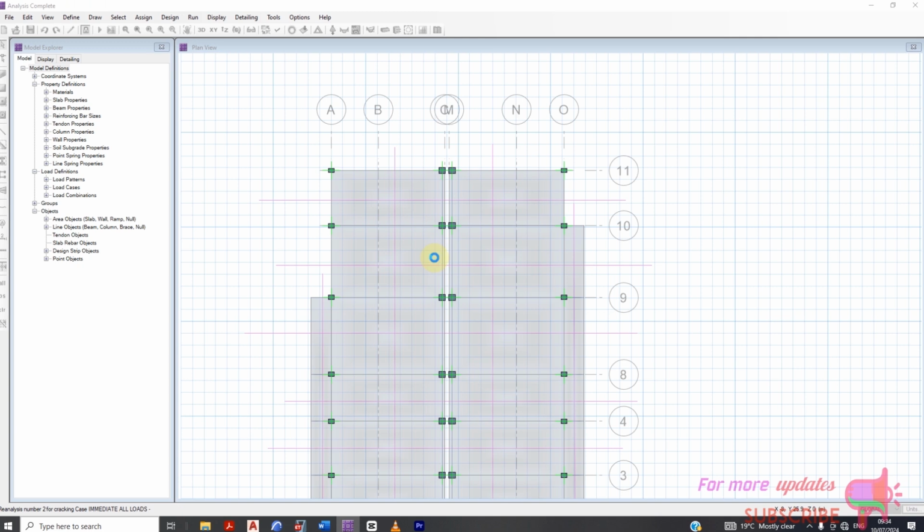So a depth of 200 millimeters or 8 inches was okay. Now let's check if this depth of 6 inches or 150 millimeters is okay in terms of deflection. Now we're going to check the critical panel and also the maximum point of deflection where we just saw.